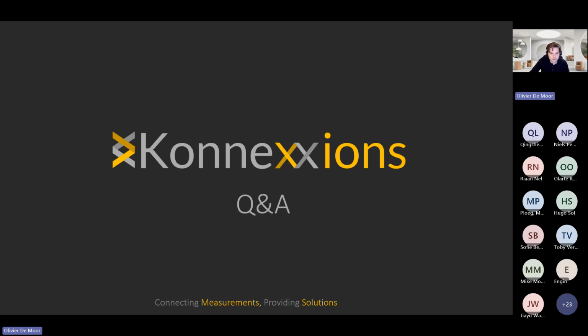So thank you, Oscar, for the question. And the question is, the frequency of the LDV is limited by the sampling time of the OROS data acquisition system, for example, OROS 04. So this depends. So our systems can now have both analog and digital output. So if you have the digital output, actually the bandwidth of the laser is limited by the configuration that you have per case. So we can have, for example, with the VibroFlex system, up to 24 megahertz. With the VibroGo, we can have up to 320 kilohertz. So that's the limitation of the systems.